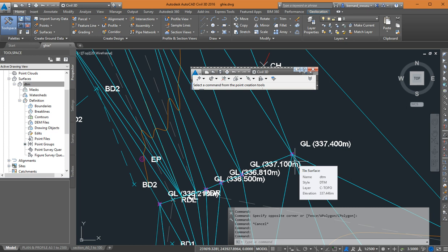So what do you do? You have to ignore that point. One is you may want to delete that point, or you can tell AutoCAD Civil 3D that in building the surface, any point that it sees with elevation below a certain value, you should ignore it, or elevation above a certain value, you should also ignore it. Please, are we okay? So we are going to try that one. The deletion, you can just click and delete. That's very simple. And rebuild. But how do you do the boundary in terms of minimum and maximum?